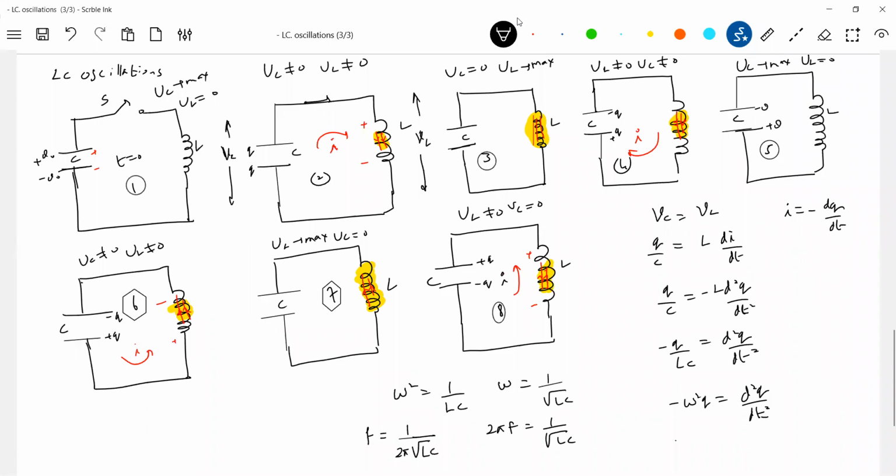So the frequency of electrical oscillations set up in this circuit depends on the values of L and C, just by varying those. Where do you use this? This is the oscillator. We want an electrical signal of definite frequency. Suppose for mobile, we use an electrical signal of around 200 megahertz. For radio communication, the FM band, we use around 88 megahertz to 100 megahertz. How do I generate an electrical signal of that frequency?